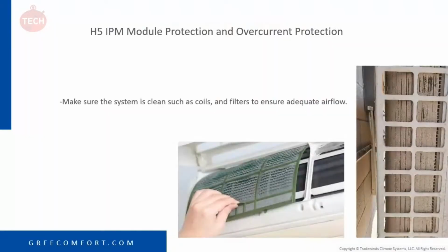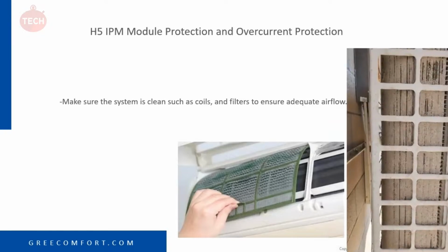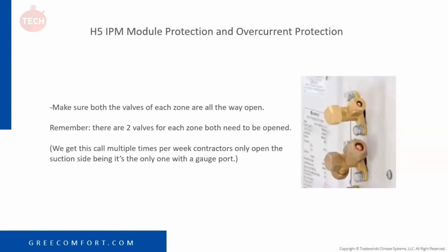A couple checks we want to do. Of course, make sure that the filters are clean, coils are clean. Definitely generate an E6 code. So you can see in the picture on the right, that unit is caked. Clean that up. It could be what's causing your issue. Zoom in on those.